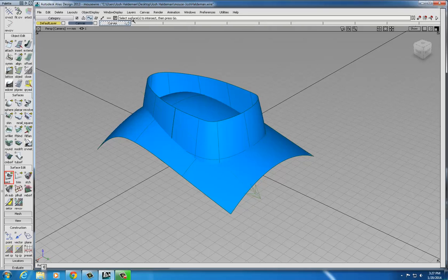It's going to ask you to select the surfaces to intersect and then hit go. In this case, just pick the top surface, not the side surfaces yet. Just the top, and hit go. Now it's going to ask you to select the intersecting surface or construction plane. This is the other set of surfaces. So pick the side surfaces. Now you'll notice that when you do this, something happens here. We get a little shape that indicates where those surfaces intersect one another, right in the middle.